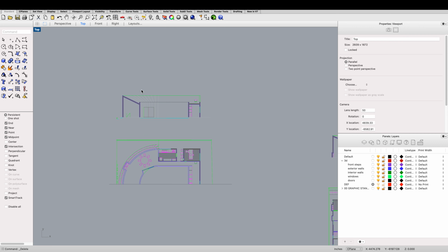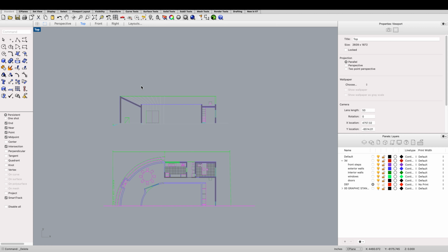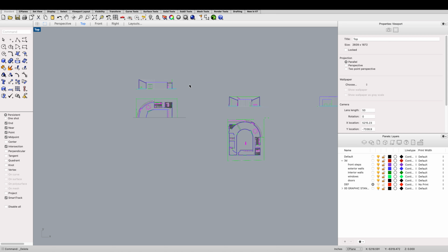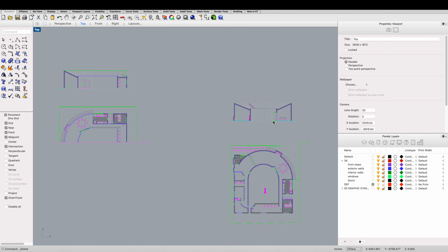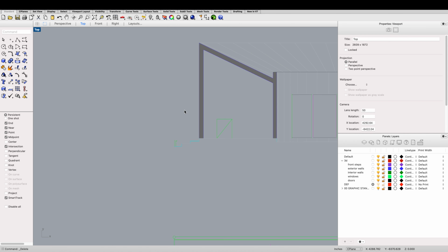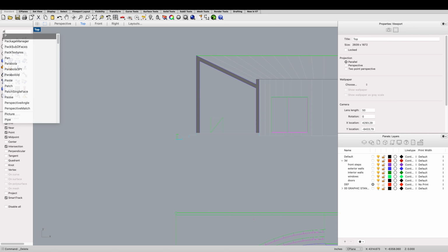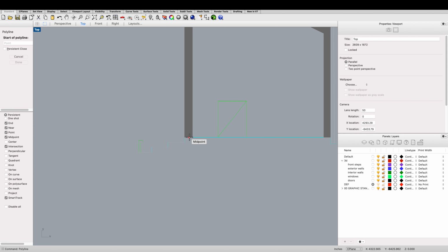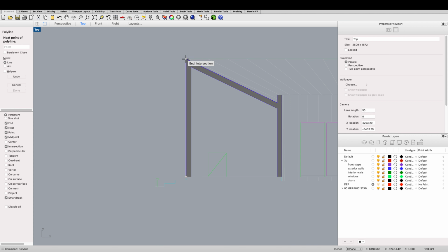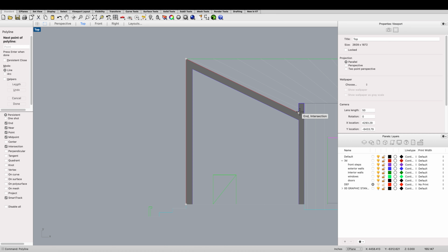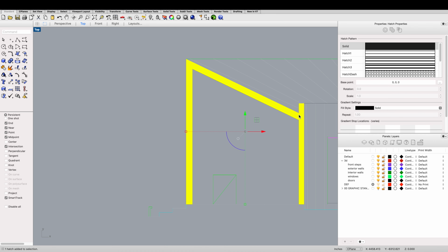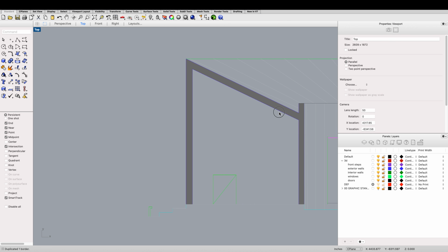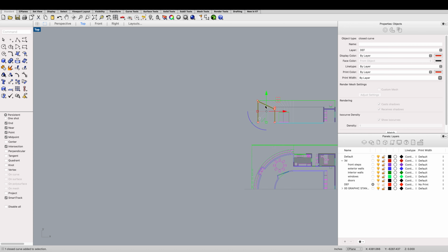What that means is we get to cheat, or it's not really cheating, but we get to sweep. So let's make a polyline and just take one profile. Or you could do what Spencer taught us, and do border. Now you've got your curve that looks like this, and we're going to move it over here.